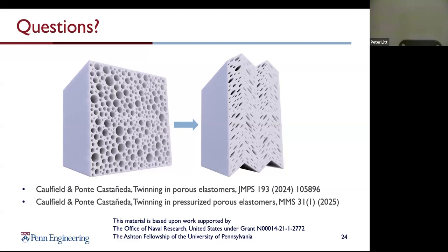Another thing I'll say is this behavior is specifically due to the way that we lost strong ellipticity. You could lose strong ellipticity in different ways depending on how your energy is behaving, and so loss of ellipticity does not necessarily lead to this type of response. It's also something people use in metals to signal shear banding. You get layers where the thing that's energetically most favorable is to localize the shear onto a particular band. That's more associated with metals, but it has to do with the way the energy behaves around there, the way it softens and stiffens in various directions. Yeah.